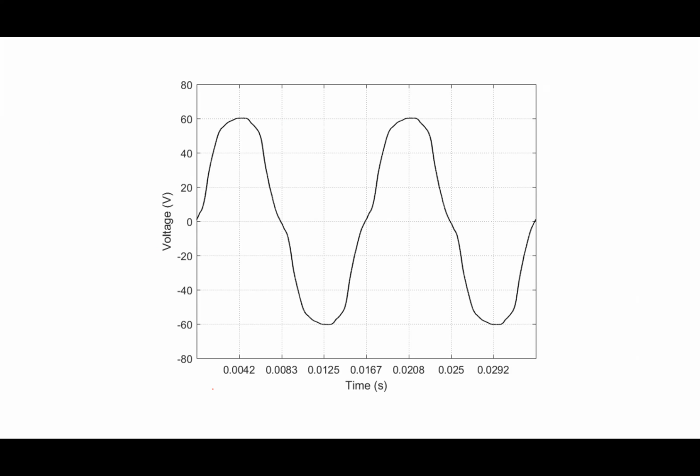Let me ask you this. It doesn't look like a sine wave, but does it look periodic? Does it meet our definition of a periodic waveform? Yeah, it does, right? What was our definition of a periodic waveform? Somebody online. X of t is equal to x of t plus... Yep. So in this case, it's the voltage. So I'll say V of t equals V of t plus a period later. Okay. So this guy repeats itself every period. It looks like it does that, right? So if I look at a peak here and a peak here, it looks like they have the same values.